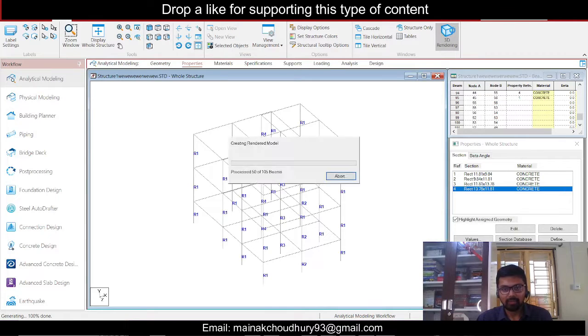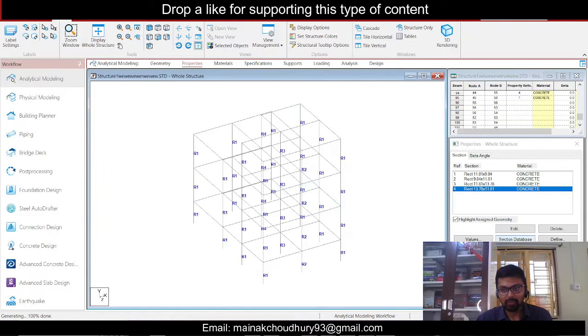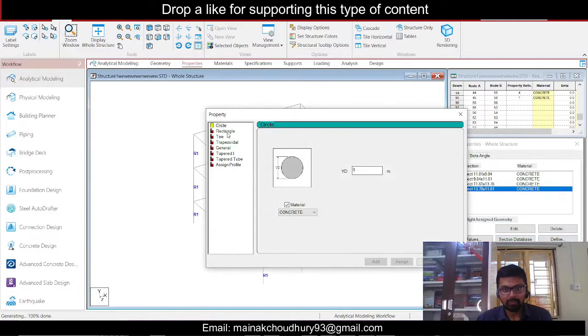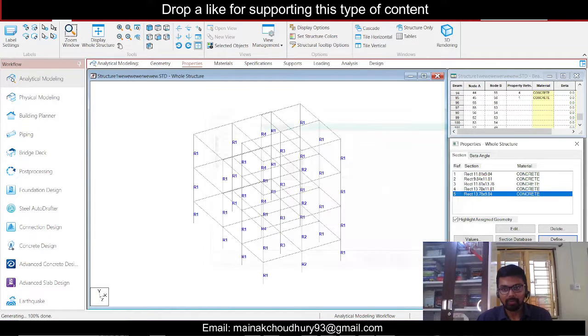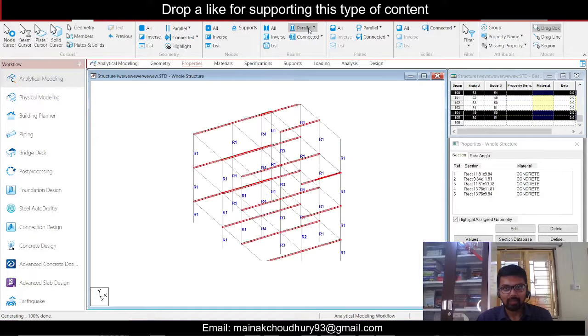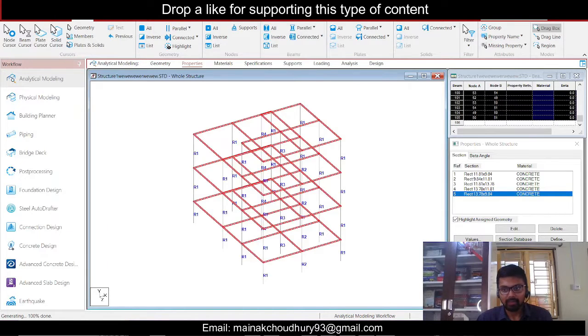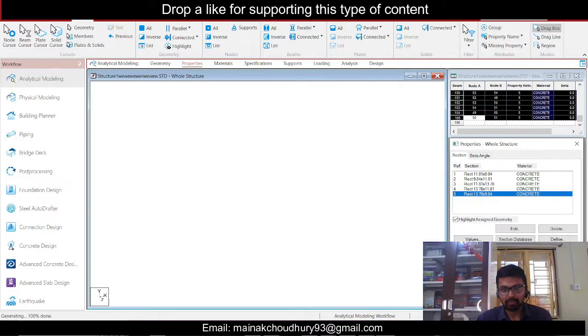You can just see in the 3D view the property assignment of the columns here. So now let's do it for the beams. We'll just define the beams as rectangle. We'll go with 0.25 into 0.35 and apply this to all of the beams. We'll select first, and then go parallel to X, parallel to Z, and then assign and yes.